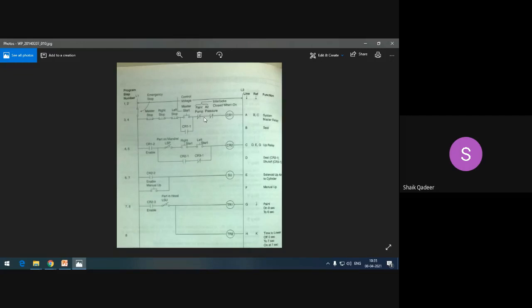Okay, you see, additionally we are also checking for this paint pump and air pressure, whether they are on or not. If they are not on, then only this process starts. And when we are triggering this first step, both the cylindrical pump and the paint pump should remain off. Then only the master start button pressing is sensed and sealed.